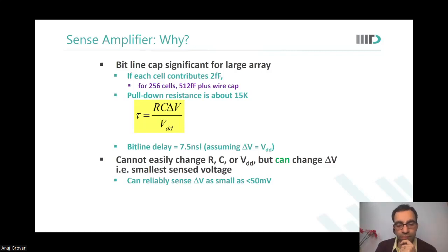Yes, sir. When you discharge less, the delay is less. If you discharge more, the delay would be more. And by using a sense amplifier, you're making your circuit faster. Because you need to discharge less, what else would reduce? We said the delay would reduce. What else? The power consumption of the bit lines would also reduce.